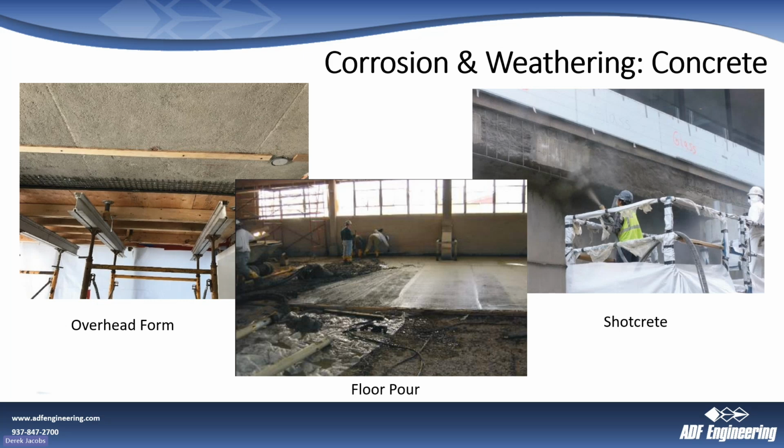You do want to contact either an engineer or a vendor specifically to find out what product works best for you, because nothing's worse than putting a whole new resurfacing on a floor and realizing that the product you selected was not specified for that level of thickness, and then it just chips away within a couple weeks or a year. And then there's even ones like this shotcrete here, which I think is always an interesting type of thing, where they pretty much blow the mortar at the concrete and have it stick to it.